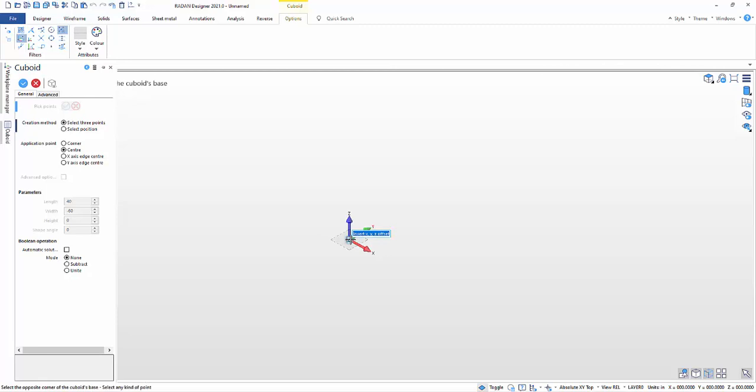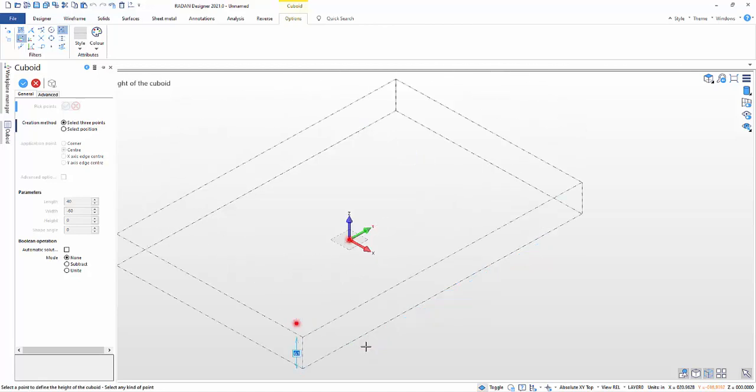From here, you can see I've got center, and I'm on the center here, and I can put my dimensions in. My box pan is going to be 40 by 60, with 1.75 inch flanges on it, and we'll go from there. It's going to be 24 deep, so I'll start here, type 40.00 tab, and then 60.00 tab, right?